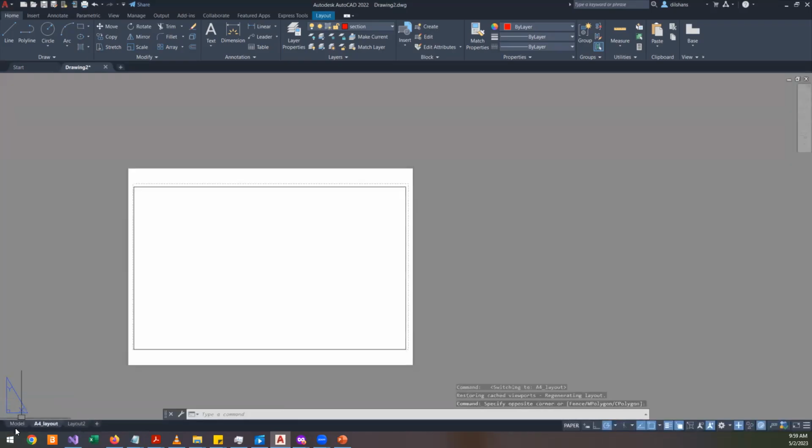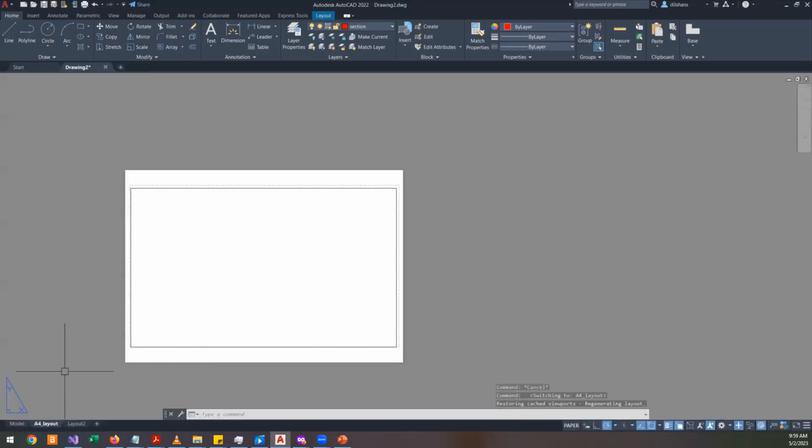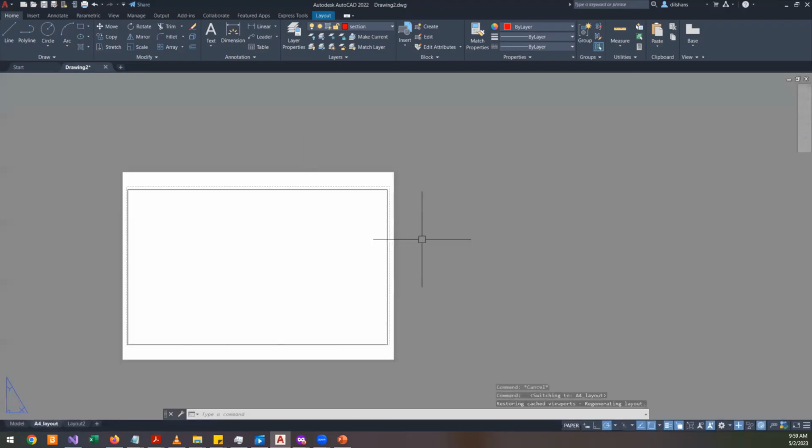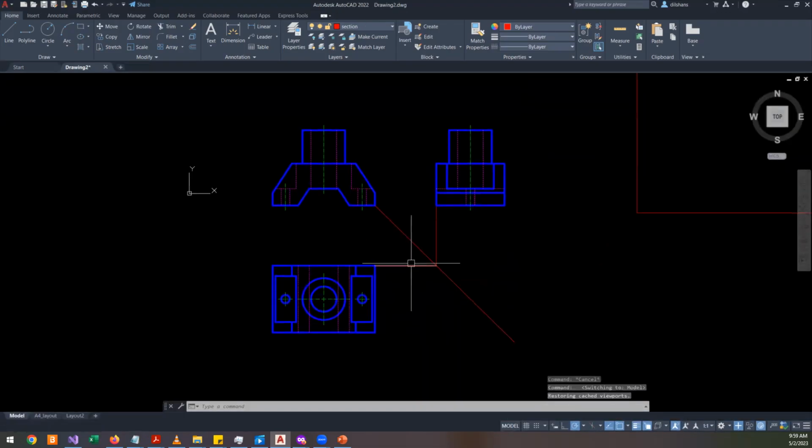You will learn that as well, but I will mainly focus on placing the dimensions or text onto this drawing area. If you are putting dimensions and text onto the layout, you don't have to worry about the plotting scale I previously mentioned. But the problem is you are not generating one drawing from this view.